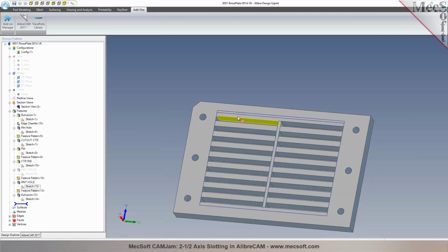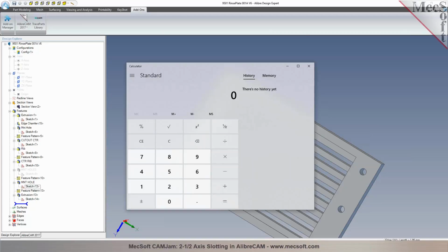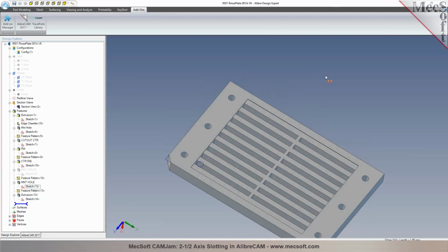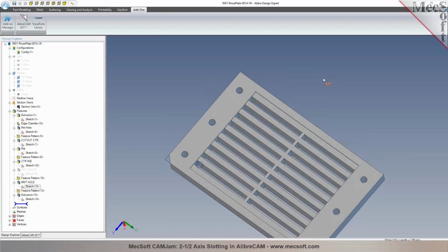Okay, so if it's 1.95, we'd have to pull up smaller than 1/8 inch, right? Let me do the math here, 1.95. So that would be 0.62, a 16th. Yeah, so you'd want to use a 16th inch cutter.